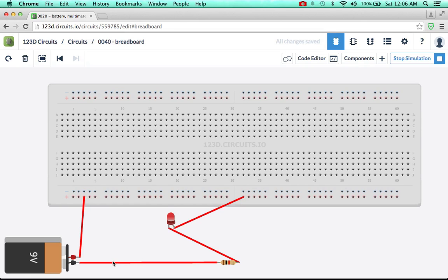And so that's the key to breadboards, is that there are wires underneath certain groups of holes that provide a connection for them. So on this row, all the holes are connected by a wire. Then there's a separate wire connecting all of these holes. And same for these two rows, and the same for each of these columns of holes. Each of these columns are 5 holes. There's a separate wire underneath each of these columns, and the same for these. And that's the key to a breadboard.